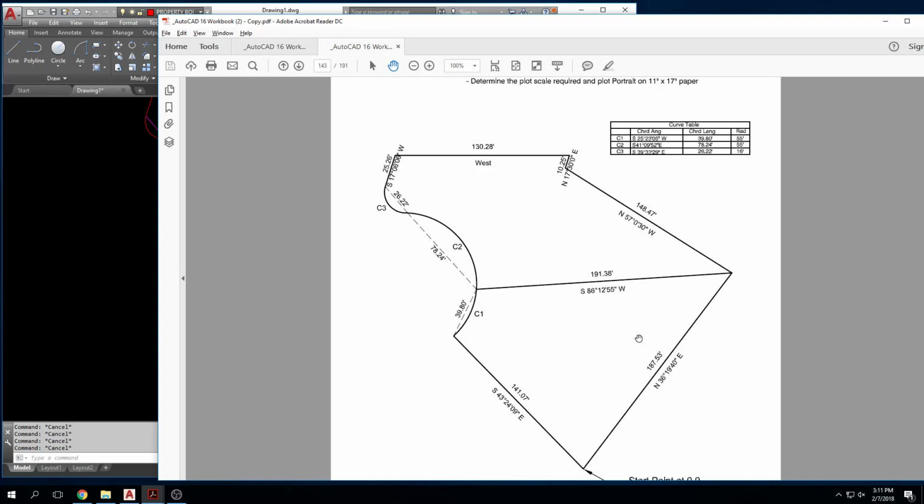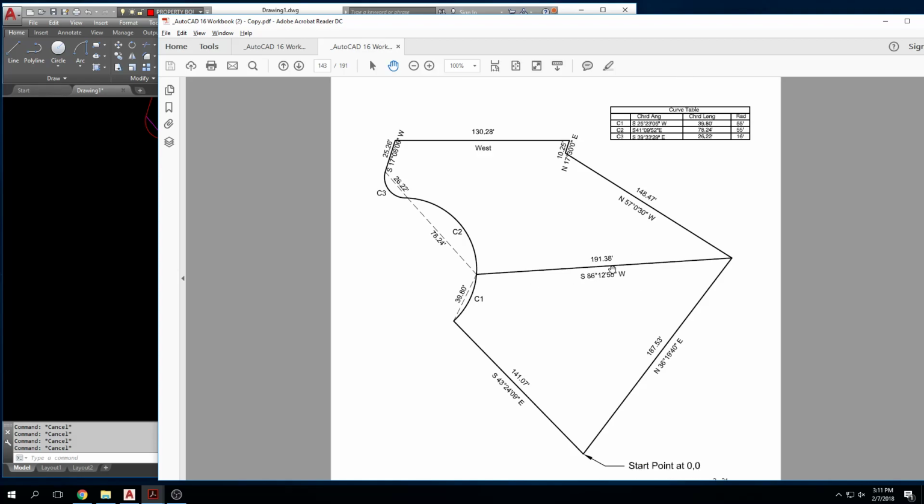Now there are going to be cases where you look at it and you think, well, maybe this was going northeast instead. If it was going northeast, it would make sense to draw it from here, right? Because this direction is northeast. So when I type that bearing in, the line would start from here and go that direction had it been opposite, right?